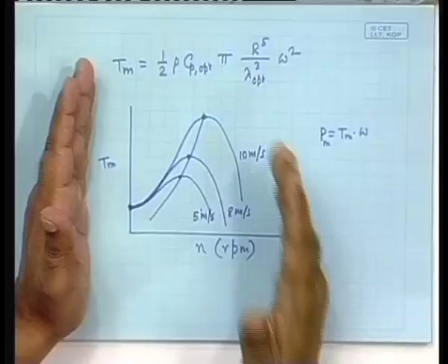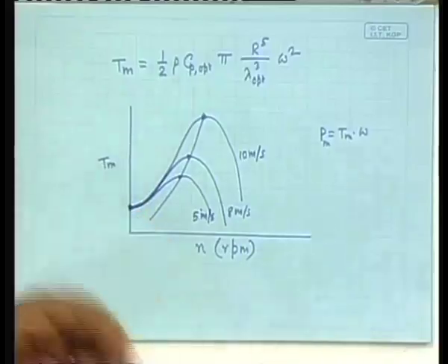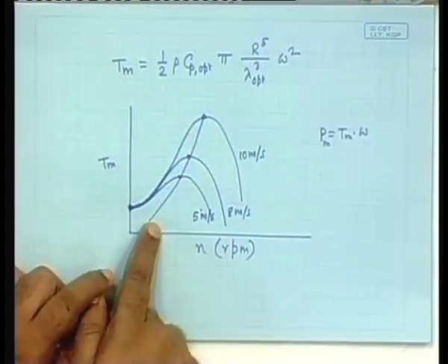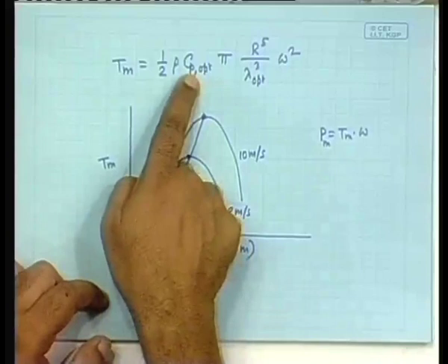So, that is the back torque that comes whenever you generate and actually use the electrical energy. Here also the same thing will happen. So, this is the character of the generated torque, and there will be a corresponding character of the load torque. Now, if this wind turbine is supplying, for example, a pump, water pumping, then the water pumping has its own characteristic feature of the speed versus the torque, okay, and these two will have to be matched. Why? Because you want to operate on this line all the time. This is related to the optimal value of the Cp.